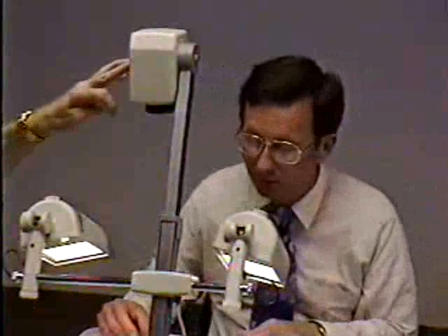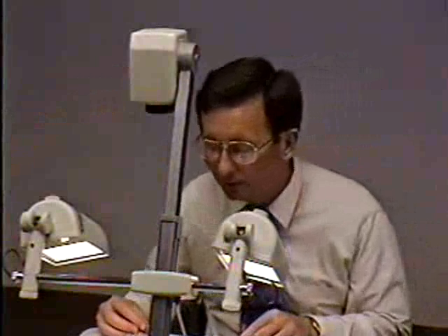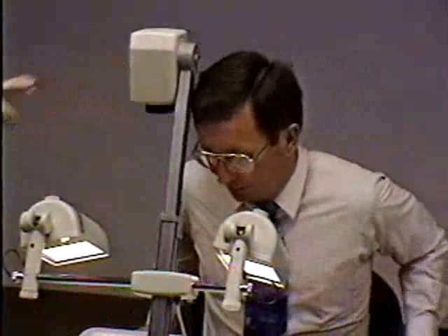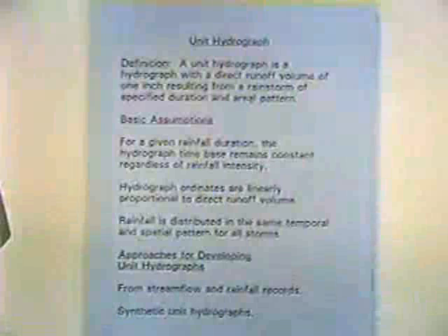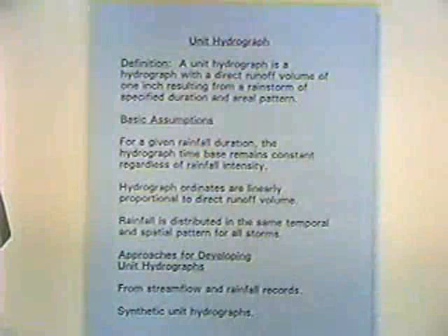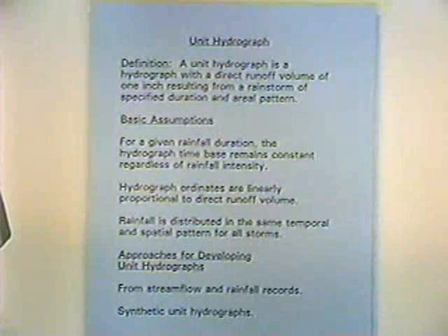We've got about 5 minutes here. Normally, I teach a graduate class in open channel hydraulics, but I also teach a graduate class in surface water hydrology, and we would spend several hours on the unit hydrograph, but I think somehow we're going to do it in 5 minutes here. And so the basic concept is this. The unit hydrograph is for large, complex watersheds. The rational method is a simplified approach for a small watershed. The unit hydrograph gives you not only the peak discharge, but the entire hydrograph for larger watersheds.